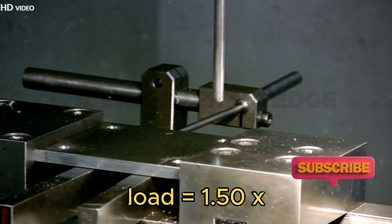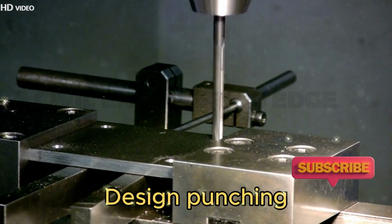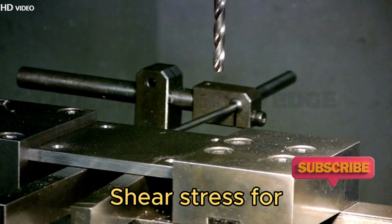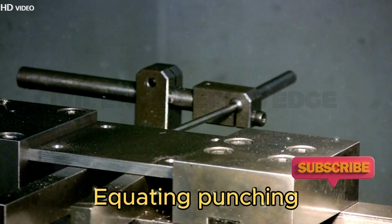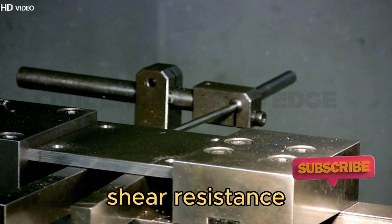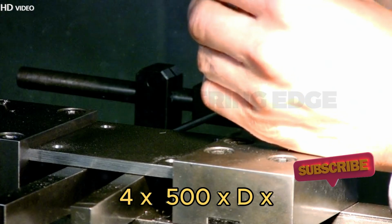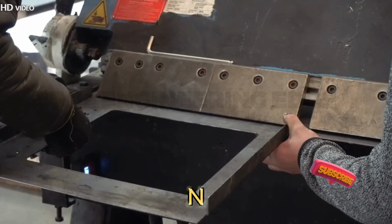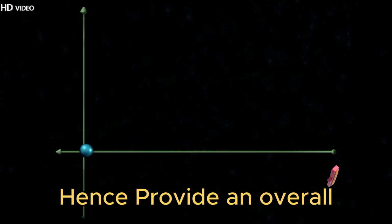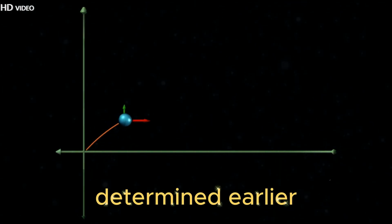Factored punching load equals 1.50 x 1,450,413 N, which equals 2,175,619.50 N. Design punching shear stress for M20 concrete equals 1.80 N/mm2. Hence provide an overall depth of 900 millimeters as determined earlier.